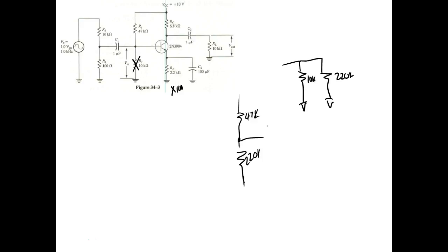And the output's going to be really distorted. My bias voltage is going to be all out of whack, right? You understand? I'm going to open up R2. I need a pair of needle-nose pliers because it's down here. So R2 is open.